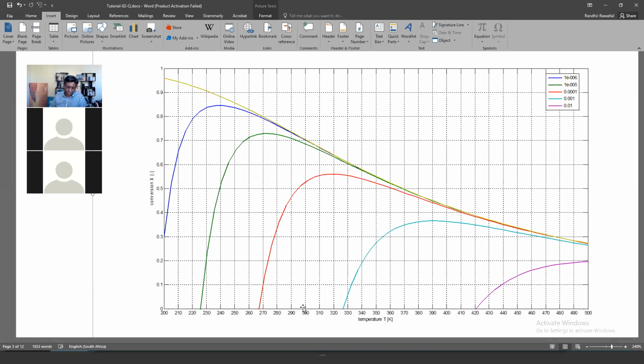And then as the reaction proceeds, of course, your conversion is going up. And we know this is an exothermic reaction, so here your temperature will rise as well. So your conversion and your temperature are going to increase in some way. And we would like to know how far should that line go? Where should we stop?